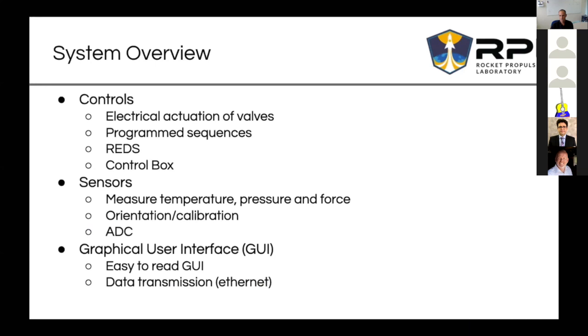The sensors team will be responsible for measuring temperature, pressure, and force at various points on the rocket to collect data for FAR, as well as monitor the status of the system during the test to verify functionality. They will also be responsible for determining the proper method of mounting to collect data and calibration for high accuracy. Lastly, they will be in charge of programming the ADCs for conversion of analog sensor data to digital so it can be input and transmitted by the microcontroller.